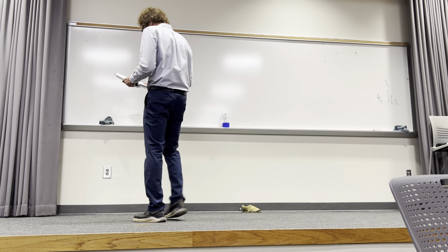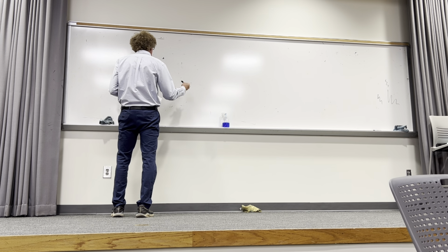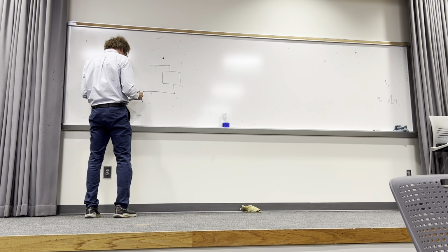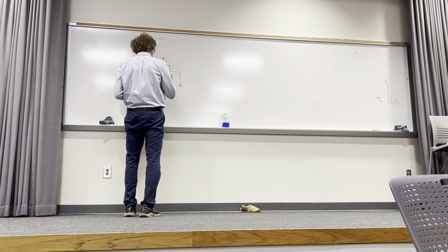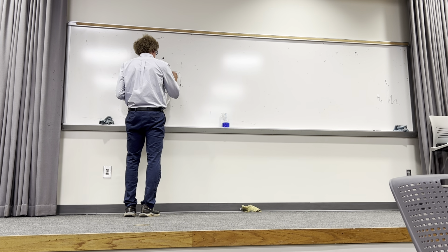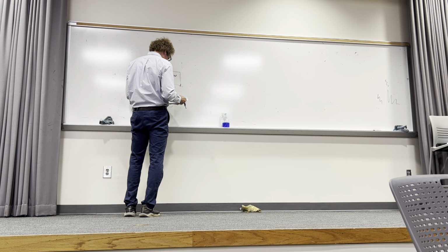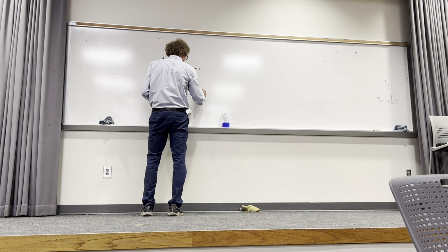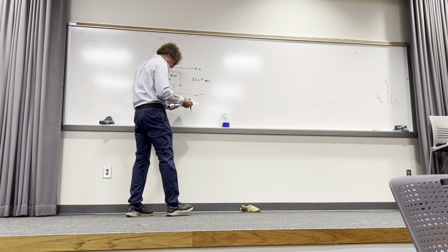So this one says an industrial power plant operates under the following conditions. And this is, by the way, single phase. The load is 40 kW, so here's the load, and it has 40 kW of real power. It's dissipated. The line voltage is 220, so here they're saying it's plus to minus 220 volts RMS. That's not peak, it's RMS here.